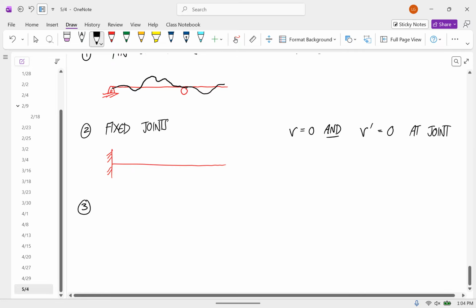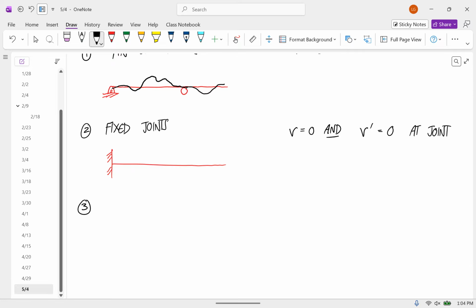And then the last thing is, remember that the internal bending moment is a piecewise function, right? We'll have one function that represents it up to a point, and then another function that represents it after. That's why we do the cuts. Okay. So at the places, I'm going to call them seams, where one cut ends and the next cut begins, there are restrictions because it has to be the same beam. And so at seams, and these are the points between cuts,